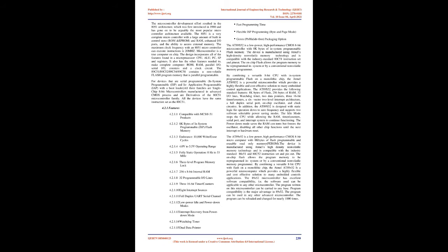For devices that are serial programmable, in-system programmable, ISP, and in-application programmable, IAP, with a bootloader, all three families are single-chip 8-bit microcontrollers manufactured in advanced CMOS process and are derivatives of the 80C51 microcontroller family. All the devices have the same instruction set as the 80C51.